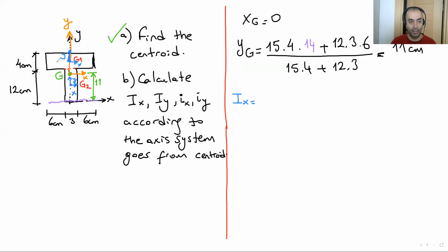What is the parallel edge here? The parallel one is this one, totally 15, times what one? Which one is the perpendicular? Perpendicular is this one, so 4 cubed. If we have a perpendicular edge, we get cube over 12. This is the moment of inertia of this rectangle at the top, for the local coordinate system.